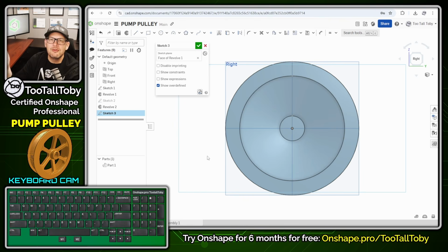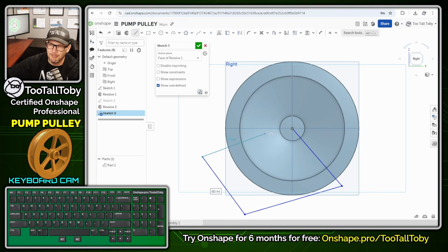And that is when you know you're sketching 2 lines and you know they're not going to be connected, you can click and drag. You can click the left mouse button and drag, and that'll make 1 line, but it'll leave you in the line command. So what I mean is normally what you do is you go click, move your mouse, click, move your mouse, and so you get a bunch of lines or a chain of lines.